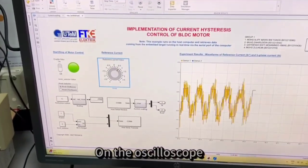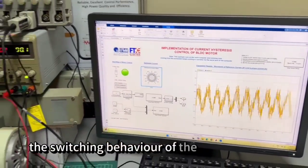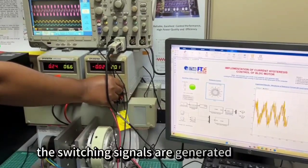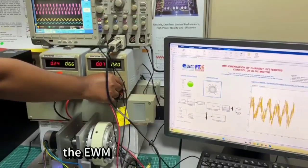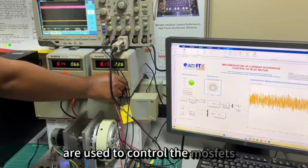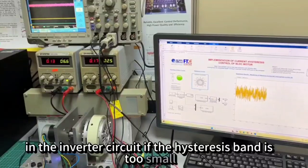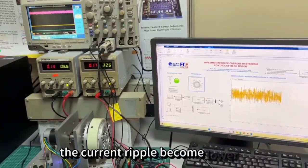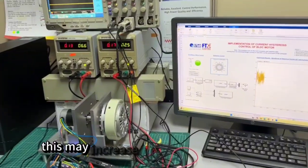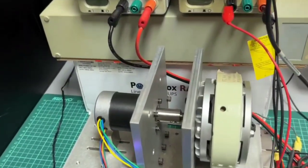On the oscilloscope, the switching behavior of the inverter can be observed. The switching signals are generated from the EPWM output of the DSP and are used to control the MOSFETs in the inverter circuit. If the hysteresis band is too small, the current ripple becomes lower, but the switching frequency becomes higher. This may increase switching losses and heating in the MOSFETs.